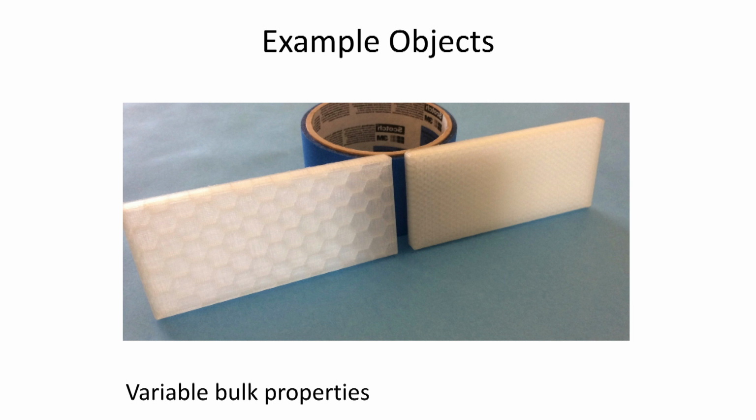So I could have a part here, for example, at a low density, that produces less stress shielding for the other materials that it is bonded to in its final application. A great example of that would be if we are using titanium femoral hip stems, we may want, with that prosthetic implant, to have our component be as flexible as possible, even if the material isn't as flexible as we want it to be.